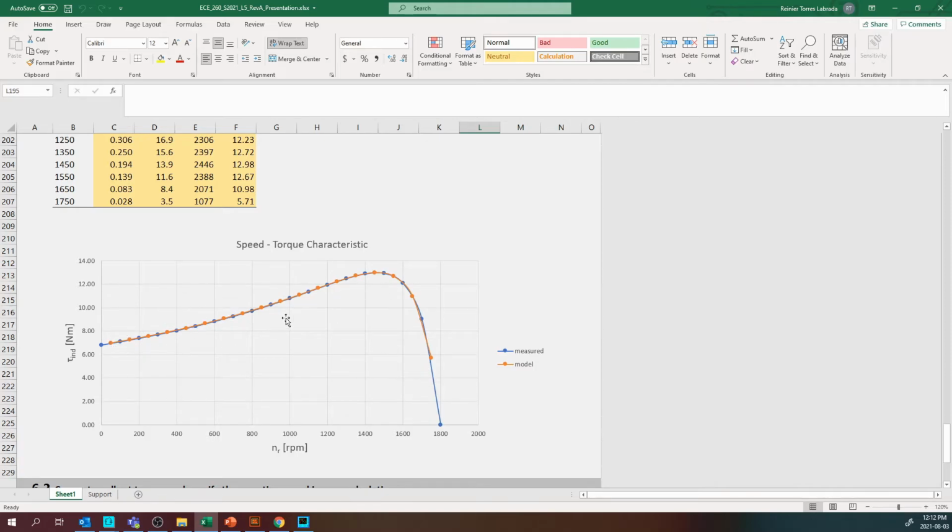We want you to be able to compute these motor parameters, so you can pretty much compute any point in this curve that you want. And that's exactly the goal of these tests. If you have a motor and you don't know its parameters, you run these 3 tests: the DC test, the no-load test, and the blocked rotor test. And from those, you compute the equivalent circuit parameters.